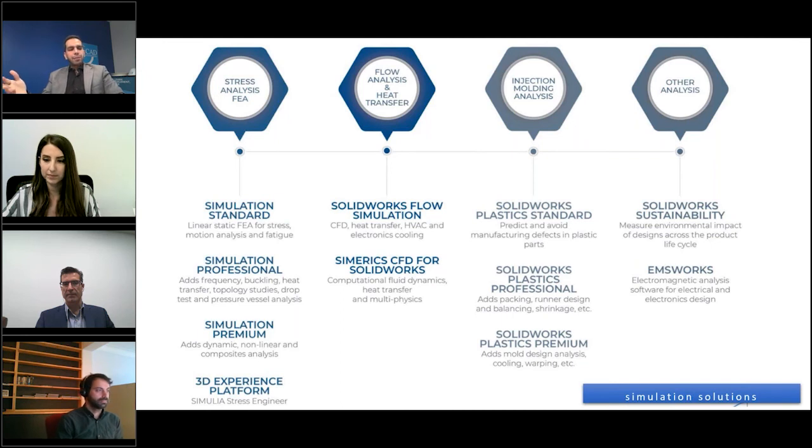And ANSYS purchased LS-DYNA 6 months ago or something around that. But that doesn't mean that LS-DYNA is integrated into the solver of ANSYS, because ANSYS is kind of Fortran, and LS-DYNA is keyword-based, and guys who have used it know what I'm talking about. So really the integration of these implicit, explicit solvers is going to be very difficult for actual applications.